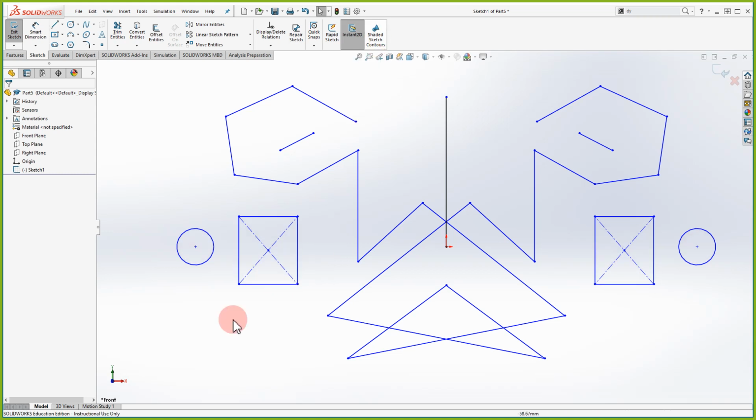So it's closed, but it's showing that it's not, if it bugs you to see the shaded in the drawing. The only difference is this is an open sketch. These are closed sketches. So when we're extruding afterwards, this would be just a thin profile, and this would be an actual solid. So that's what I want to show you with the dynamic mirror and the mirror entity.